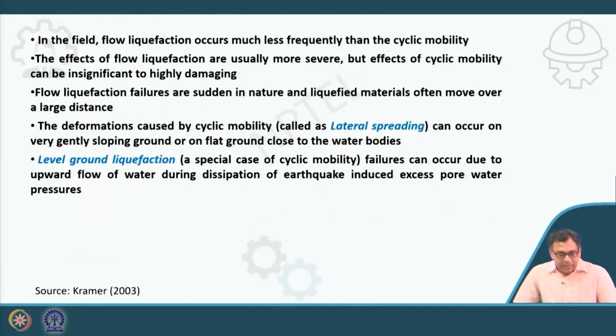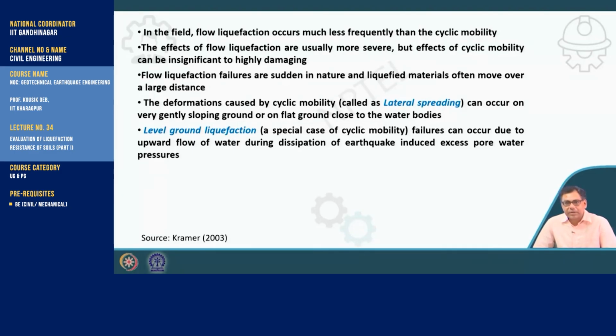So you can see that in case of flow liquefaction, your cyclic shear stress is greater than the shear strength of the soil. That means there is a tremendous reduction of the strength of the soil due to generation of excess water pressure during the rapid loading under undrained conditions. So that's why the flow liquefaction can occur in loose sand.